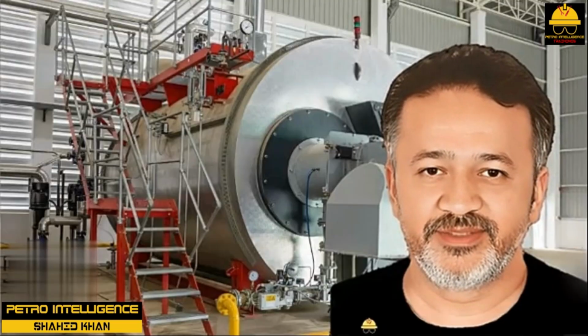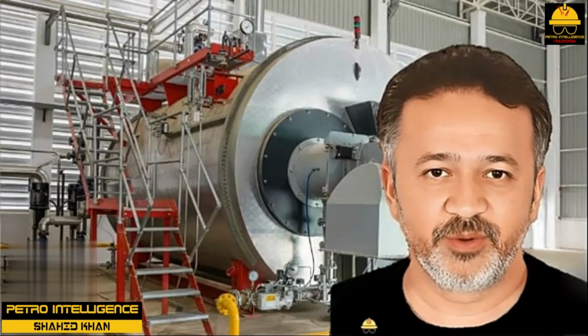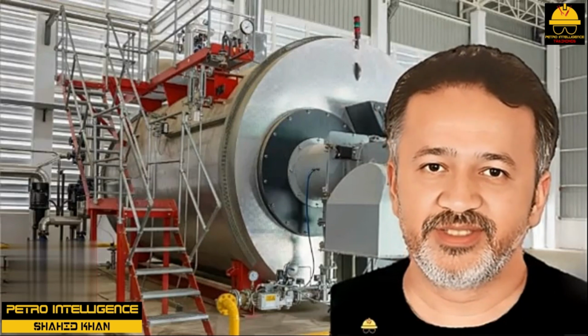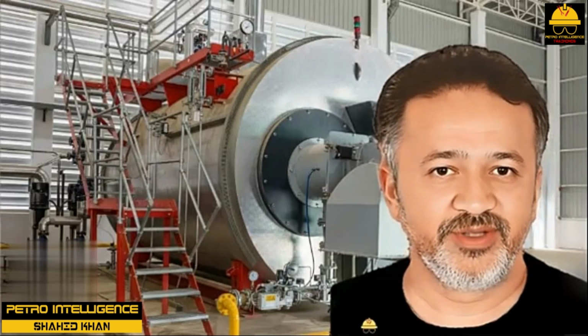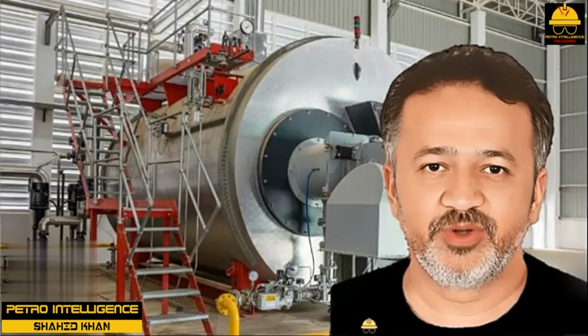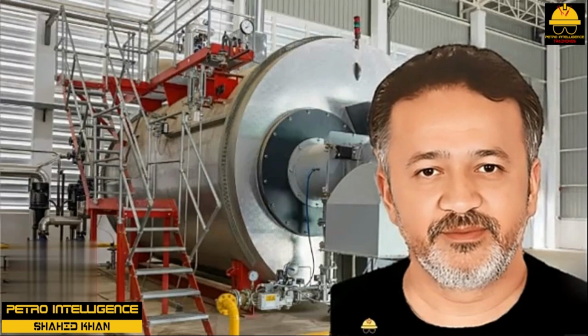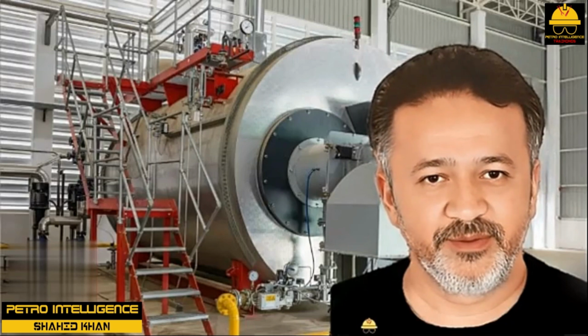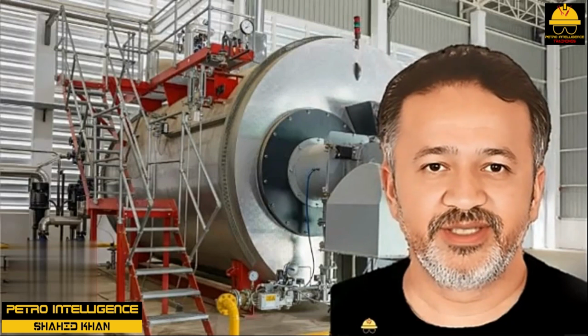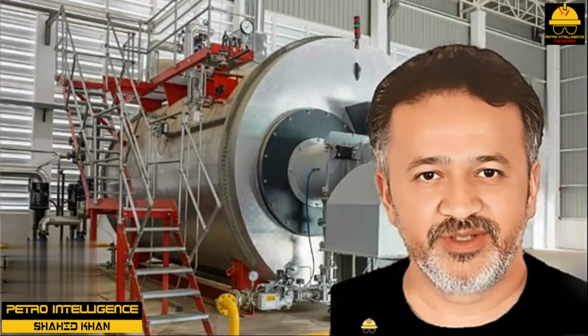Channel head leaks. Varying the steam-to-condensate interface level to control the reboiler duty will promote steam leaks in the channel head-to-shell flanged closure. This is caused by the thermal cycling and stresses that result from constantly varying the level of condensate in the channel head. However, when low-pressure steam, less than 60 psig, is used, this becomes a minor problem, which may be safely ignored.